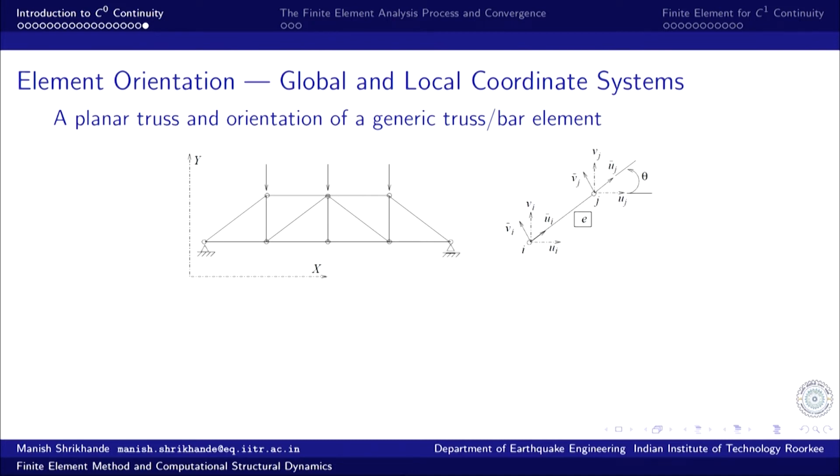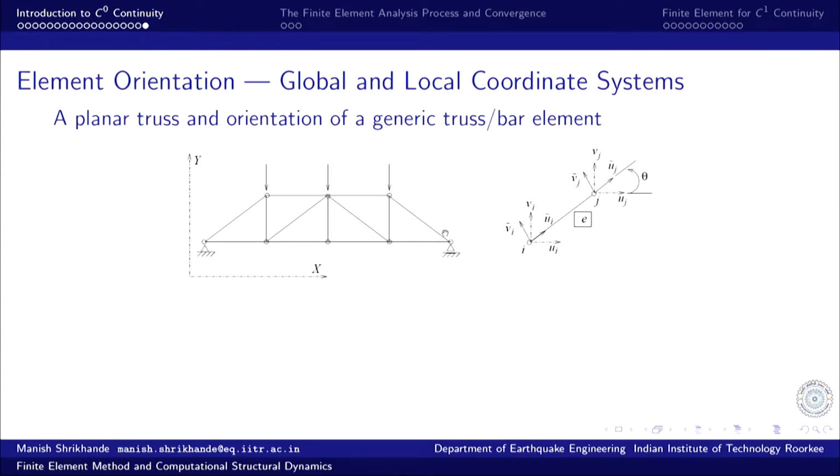So the element level equations are transformed to this new basis, and then they are used for assembly of equations. So that when we go element by element through the entire structure, after transformation, all the element level equations are referring to the same frame of reference.